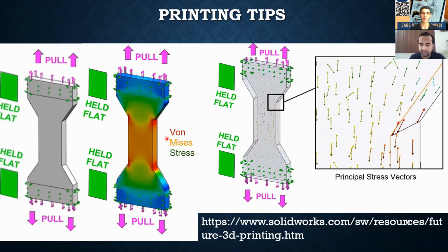I think for those that I'm not sure what FEA is, it stands for finite element analysis. Yes. Or finite element modeling. Yeah, so finite element analysis, you essentially take your 3D model, you mathematically solve a series of different equations across the entire structure. And essentially, you can remember when you're doing force body diagrams and figuring out the forces on its own little body back in physics. It essentially does that, but across the entire structure. So based off certain forces and what's moving, what's not moving, you can figure out the stresses throughout your entire structure, which is very useful when you're making something.